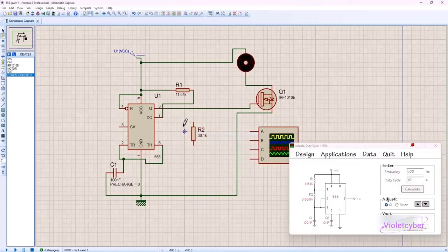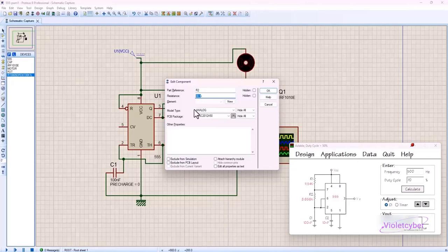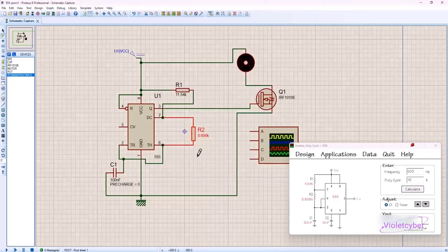Again, we'll take it from pin 7, this resistor, and this resistor comes directly to pin 2, which actually becomes 1 with pin 6, as if it is connected to 2. You see it is connected to 2. And on the other hand, it is actually connected to the ground, but we also put this resistor, that is 8 kilohms.